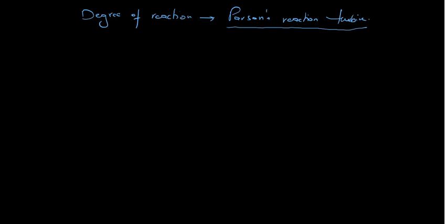Wherever you find that 50% of the expansion is taking place on the moving blade and 50% of the expansion is occurring on the fixed blade, that means it is equally distributed, then we call that reaction turbine a Parsons reaction turbine. Okay, what is the specification? What is the importance of this Parsons reaction turbine?